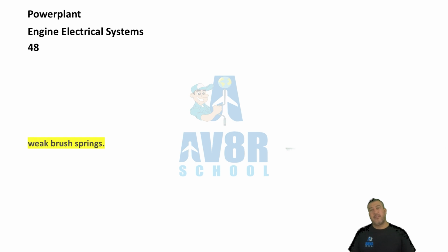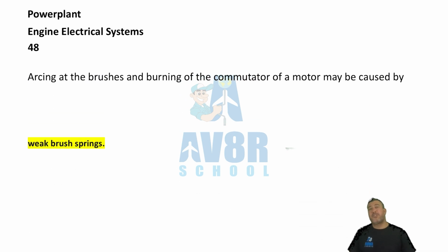Number 48. Weak brush springs. Arcing at the brushes and burning of the commutator of a motor may be caused by weak brush springs.